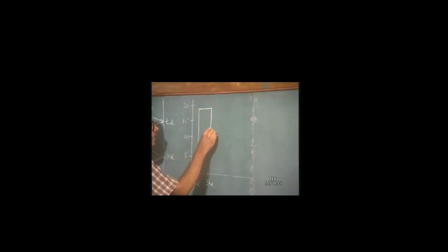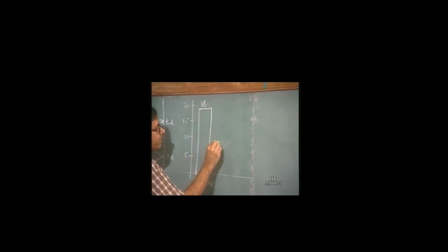So at t equal to 3 Td, if you go back to this diagram, the voltage is equal to the sum of all these components: 10 volts plus 8 volts minus 5.36 minus 4.29. This voltage is due to the wave which started off 3 Td back and underwent this reflection, and the wave which started off Td back and underwent this reflection. So we have to add up all these components, and we find that this goes down from 18 to 8.35.